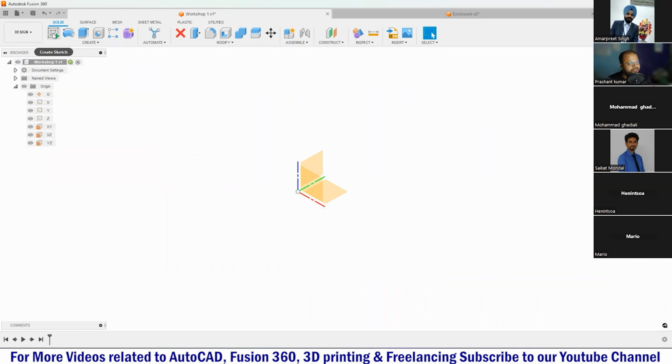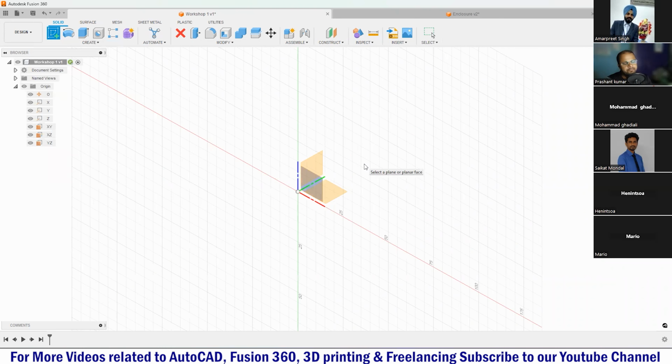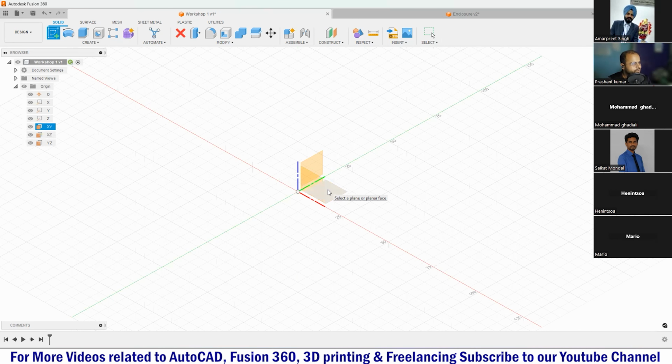So the moment I click on the create sketch tool, the first thing I have to define is the plane, on which plane you want to create the sketch. For example, if I am doing a drawing, the first thing I have to identify is on which paper I want to create my drawing, and I have to make sure that paper is flat, right? It must be kept on a table in a good condition, otherwise it will get tampered. In a similar manner, once you start your sketch inside Fusion 360, you have to specify in which plane you want to create your sketch.